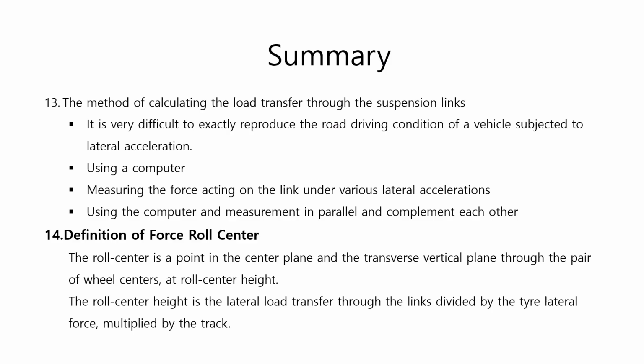When looking at the method of calculating the load transfer through the suspension link, it is very difficult to exactly reproduce the road driving condition of a vehicle subjected to lateral acceleration. There is a method using a computer and a method of measuring the force acting on the link under various lateral accelerations. The best method is to use the computer and measurement in parallel and complement each other.